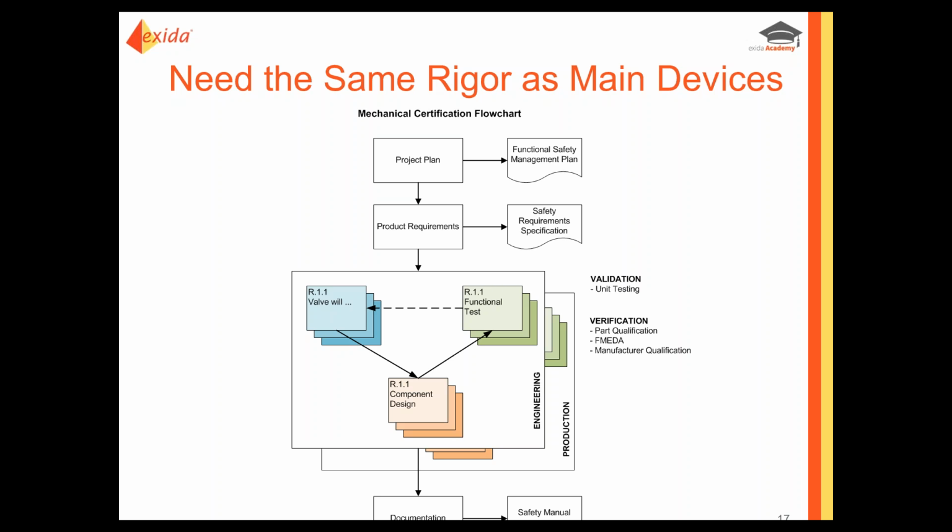It's not that every bracket manufacturer has to be 61508 certified, but there should be some traceability or some methodology to show that yes, we used good design principles, we had a specification, we designed to it, we recorded the results, and here's our objective evidence that this design is valid and will work. So there is a degree of rigor and traceability that is required in both the design of these components and the production and assembly of these components.